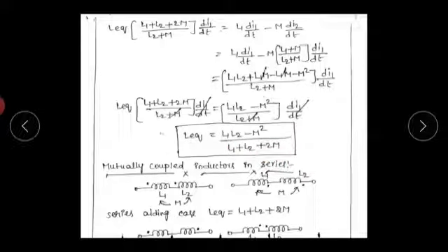Okay, this is the equivalent inductance formula in parallel opposing connection. In parallel aiding connection, there is minus 2M, and in parallel opposing connection, plus 2M. So the equivalent inductance in parallel aiding connection is more compared to the equivalent inductance in parallel opposing connection. In parallel aiding connection, there is minus 2M; in parallel opposing connection, there is plus 2M.